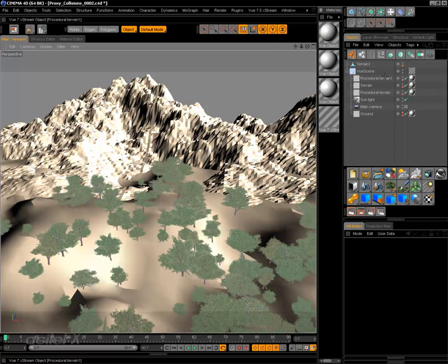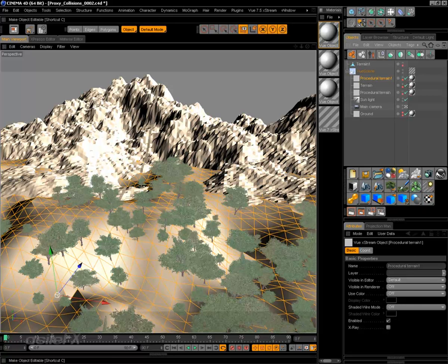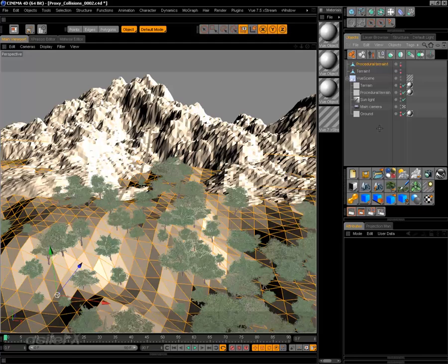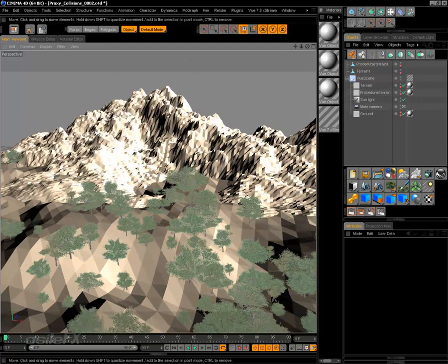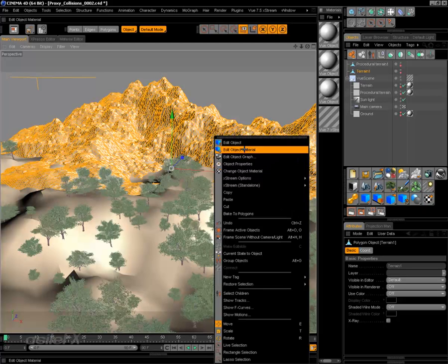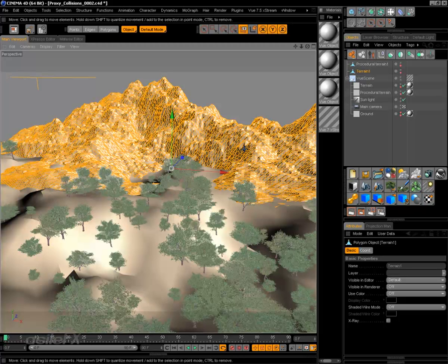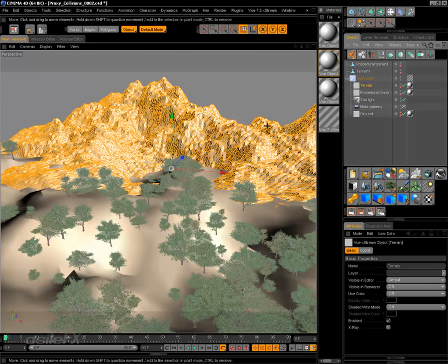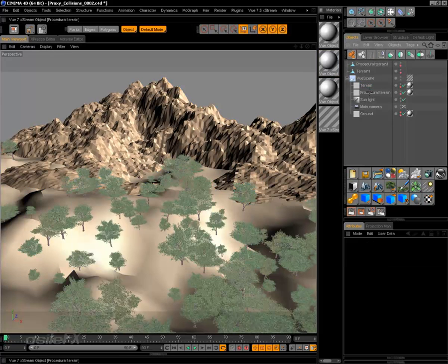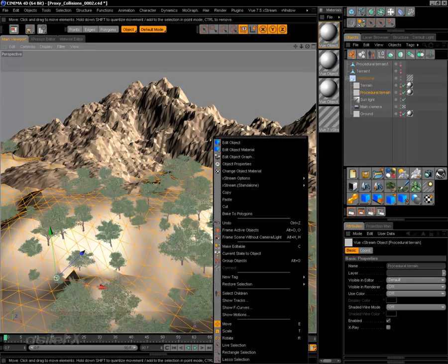And now that new terrain is going to show up, we can go ahead and make it editable and drag it out of the volumetric and delete any tags attached. Because I did reload, it refreshed the materials, so I'm going to select our objects, edit the object material, just click OK to close it out, just to regenerate those colors.